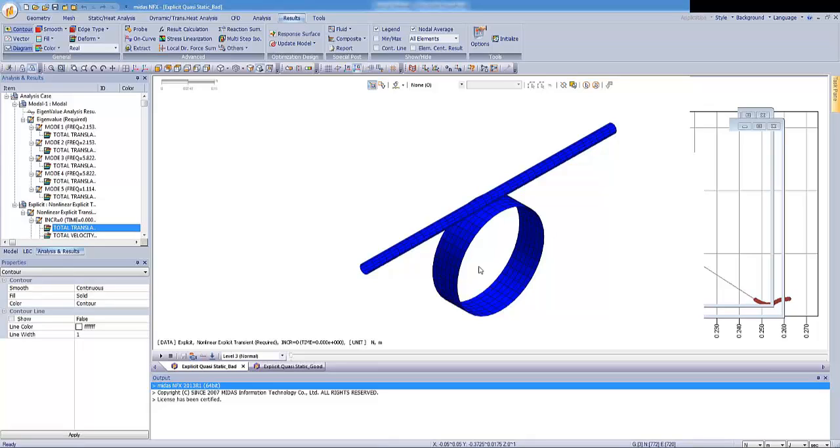So let's take a look at the example shown on the screen. We see two objects. The big rigid cylinder is impacting a deformable beam. In this model, nonlinear material has been added and both of the ends are fixed. As the dynamic load, I use a time-dependent displacement, and the value for this displacement equals 0.1 meter.